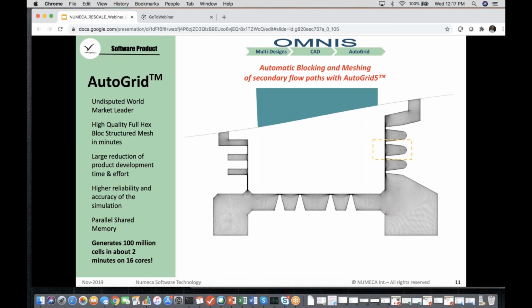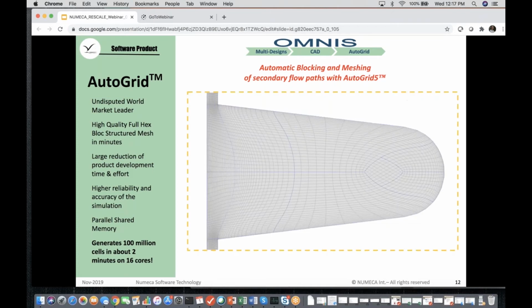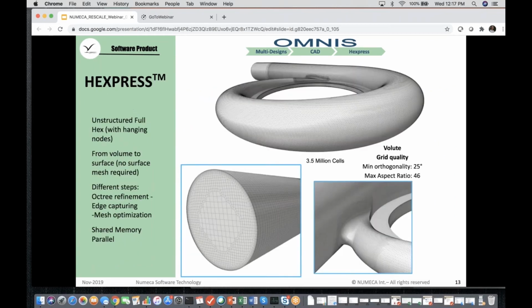We've actually pushed the limits of what you can do with multi-block structured meshes by including additional things such as ported shrouds, cavities, leakage systems, such as the one you see here, and still have this high quality with multi-block smoothing. So that's for turbomachinery passages. When the geometry becomes more general, and there you can think of anything.